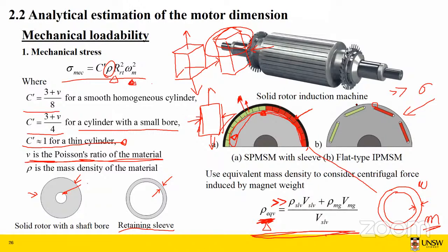You need to use other, more complex analytical models to calculate stress. You need to calculate a reference stress, and you also need to know a stress concentration factor. You multiply these two values together, and you get the maximum mechanical stress.